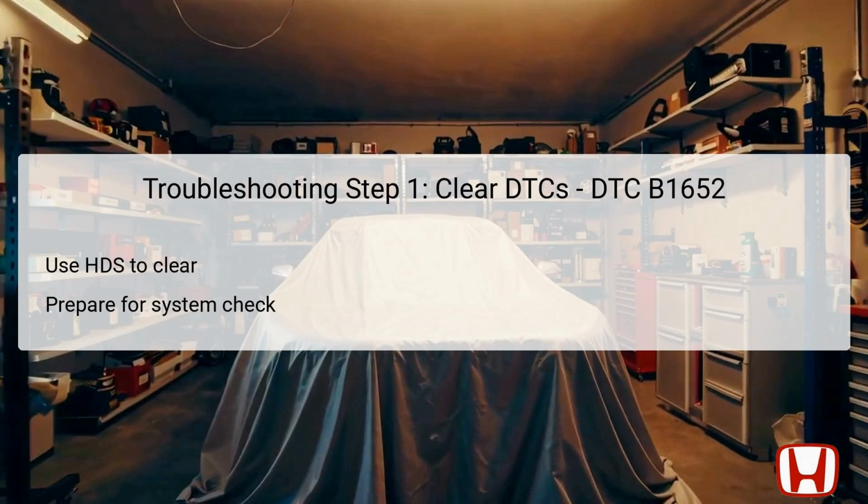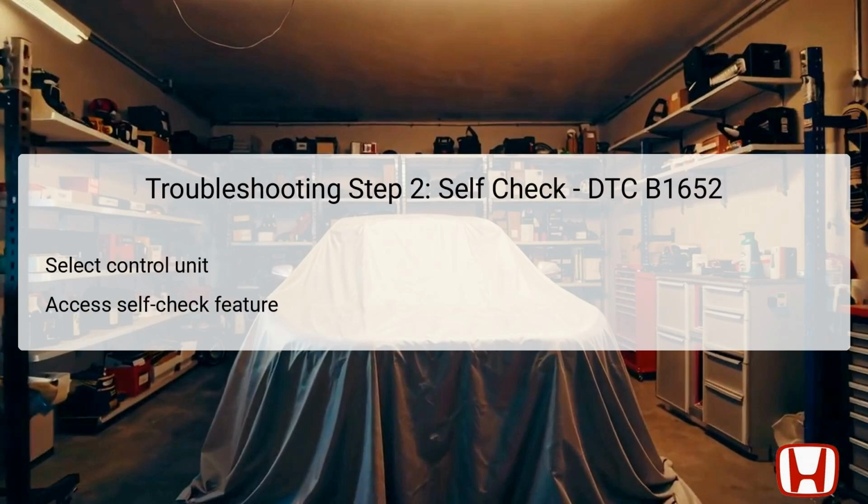By doing so, technicians can determine if the B1652 code reoccurs, indicating a persistent issue that needs further investigation. Understanding this initial clearance procedure helps streamline the troubleshooting process and narrows down potential causes effectively. In the second troubleshooting step for DTC B1652, one must access the keyless access control unit through the HDS.